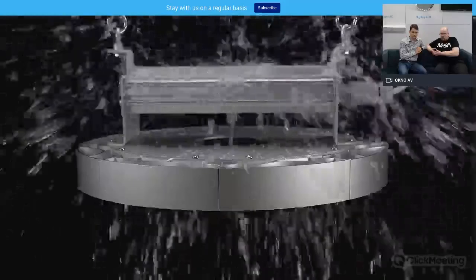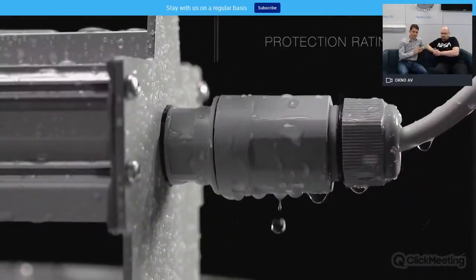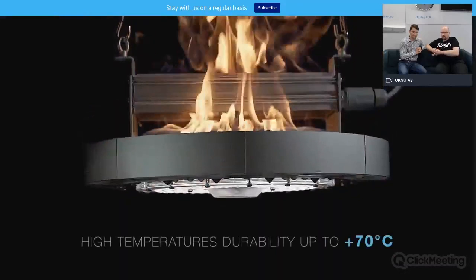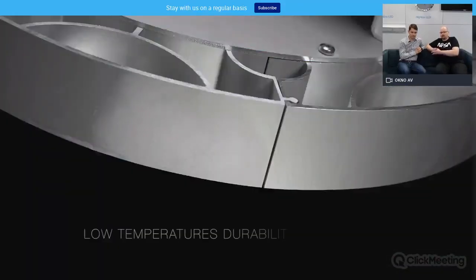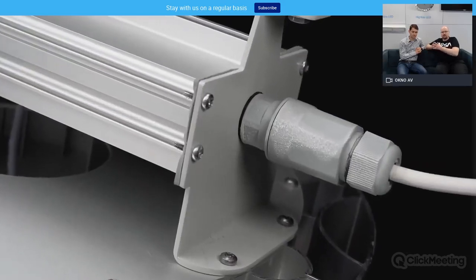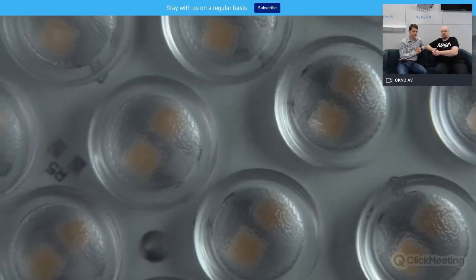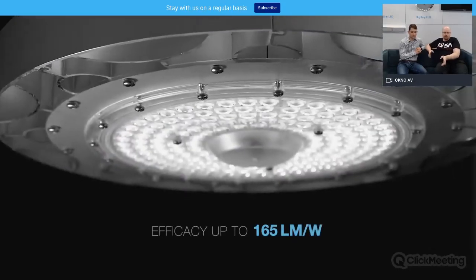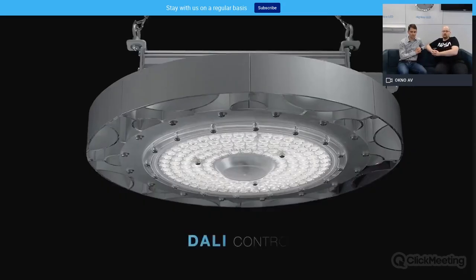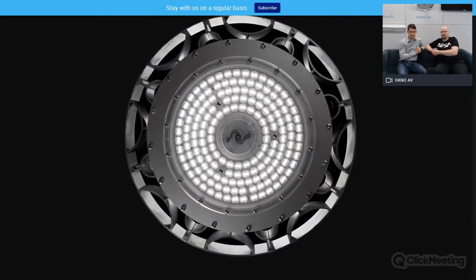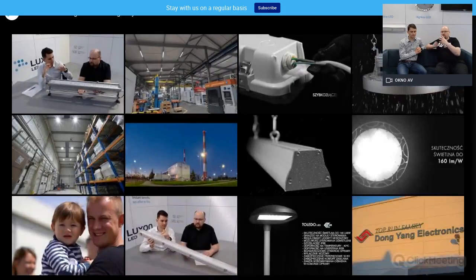First of all, aluminum construction, anodized, resistant to water. Yes, IP65, of course, IK8, lenses made out of PC because it's not a brittle material, it's a material that will withstand from -42 even +120 degrees in terms of the lens material, which makes it perfect for the solution. This comes with an option for the temperature range between -35 to +70, depending on the version. So, a broad range of temperatures. Again, you have lenses with 90 and 60 degree beam angles, which is perfect for greater mounting heights, such as 8 meters, 10 meters, 12 meters.